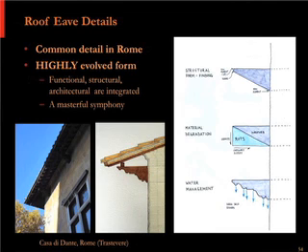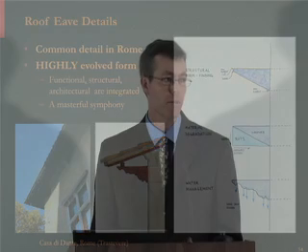So let's break it down piece by piece. Well, structurally, that main member that comes out and supports the roof overhang, the moment diagram on that is going to be a triangle. So kind of the shape it wants to be structurally is a triangle. And it wouldn't come exactly to a point, it would have a little bit of a blunt end because even though there's no moment at the end, there is some shear. And then the maximum moment would be back at the deepest point of the triangle against the wall. And then if that supporting element were out in the weather and getting wet, the way it would rot looks like the middle one down on the right.